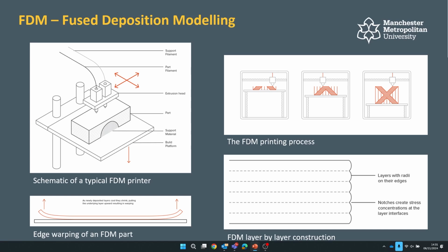Now, this one in particular is what we call FDM 3D printing, fused deposition modeling. And what this means is it's got a hot end, so the little extruder part of the 3D printer, and it gets to about 190 to 230 degrees C, very hot, don't touch it. It will squeeze some plastic, typically PLA or ABS, and force it through this hot end, almost like a hot glue gun, but in a controlled manner based on those images it creates from the slicing.